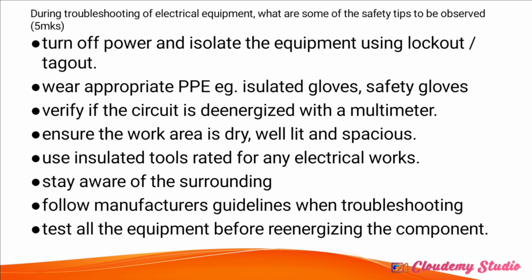Then after you have done all that, test all the equipment before re-energizing the component. That's where we always fail. A person will finish troubleshooting an equipment and immediately put on the power. If you turn on the power, you might have done the installation wrongly. You might have done it in a poor way. So you end up making the situation worse.